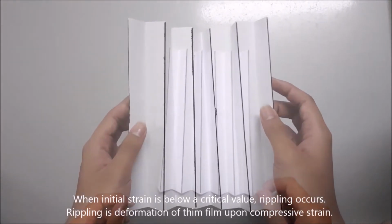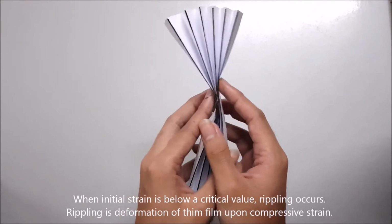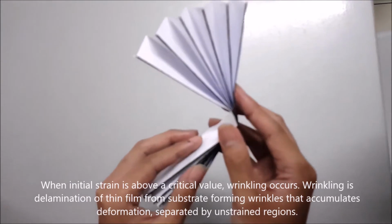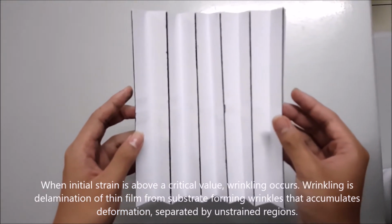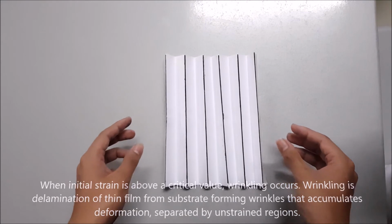When the initial strain is below a critical value, rippling occurs. Rippling is the deformation of the thin film upon compressive strain. When the initial strain is above a critical value, wrinkling occurs. Wrinkling is the delamination of the thin film from the substrate, forming wrinkles that accumulate deformation separated by unstrained regions.